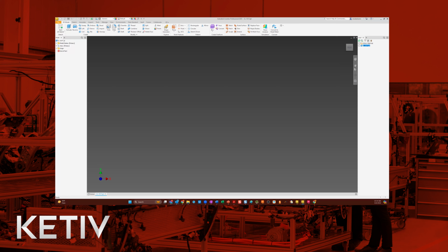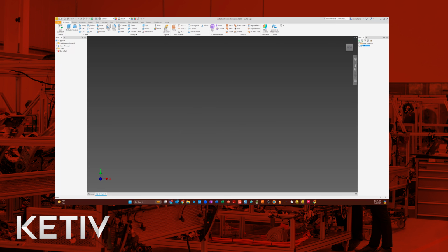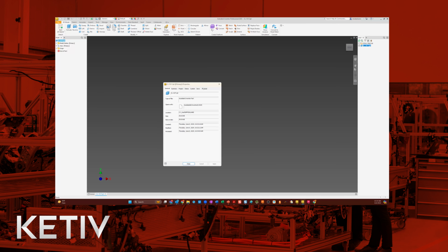Also to note, we're going to come here to iProperties, go to custom, and recall this was blank originally. Now it's been populated with all the custom properties because of the data standard here. And we will show that step as well, how those get generated in the property mapping.